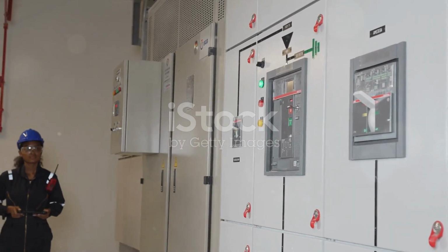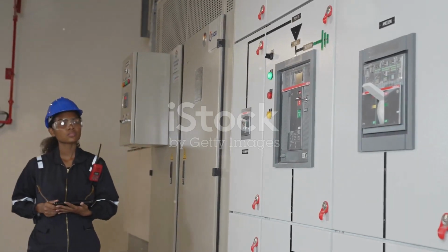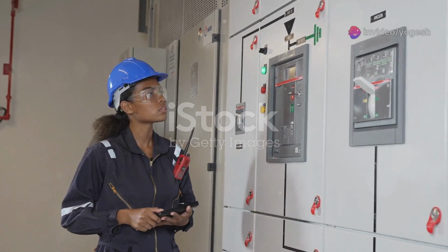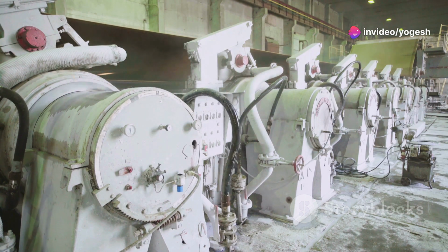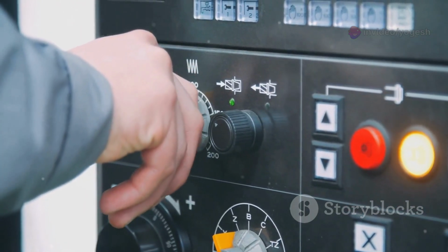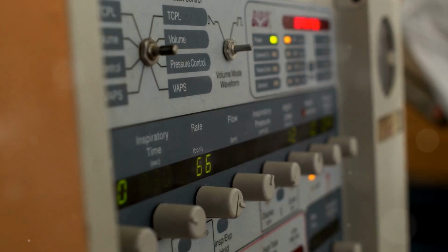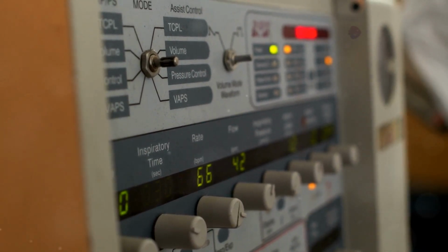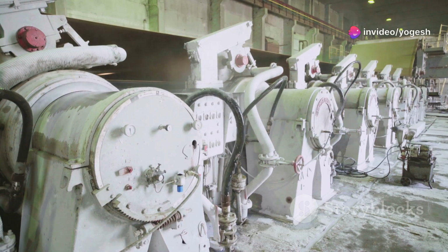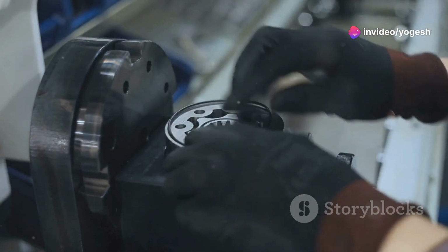Section 7. Tuning PID. The art of perfect control. Having a PID controller is great, but it needs to be tuned. Tuning means adjusting the P, I, and D parameters. These parameters are called gains, Kp, Ki, and Kd. The goal is to get the best performance. You want minimal overshoot and no steady-state error.